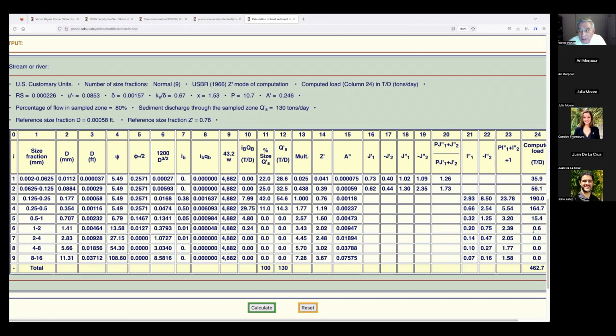I think I already said, and I'll repeat it based on experience. When you do a hydraulic computation, like Manning's, if people give you the Manning n and the cross-section, you can't make a mistake because everybody knows the answer. So 1 or 2% would be appropriate. More than that, it is in error. But in hydrology, given the fact that hydrology is a little fuzzier, you can have 10, 20, even 30% error in hydrology. There's even larger errors.